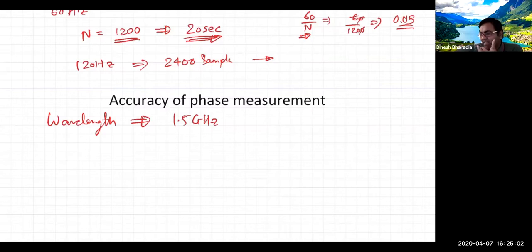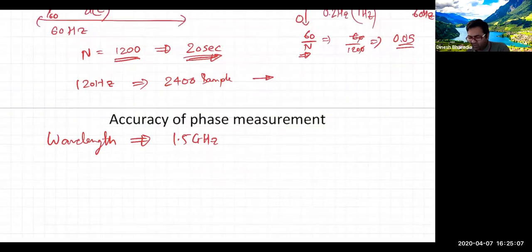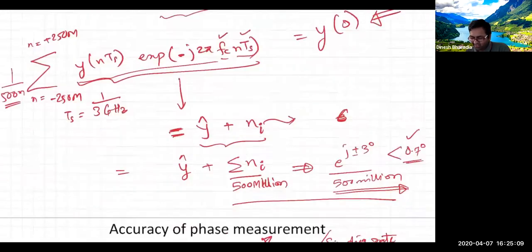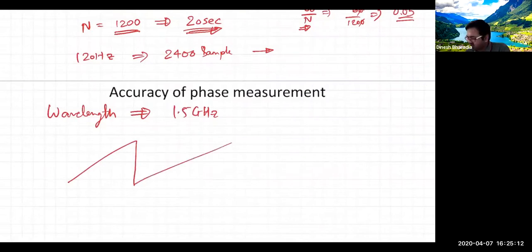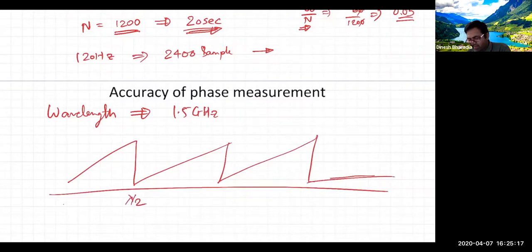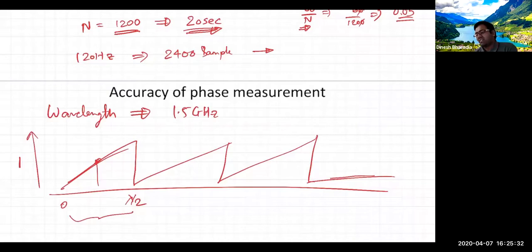It's very carefully designed so that we don't go over one wavelength, distance d here has to be between 0 and lambda by 2, and the phase accuracy also needs to be something like this on the y-axis, and the sampling rate and all these things need to be chosen very carefully. So it's very fragile in some ways. Does that make sense to everyone, how it's fragile?